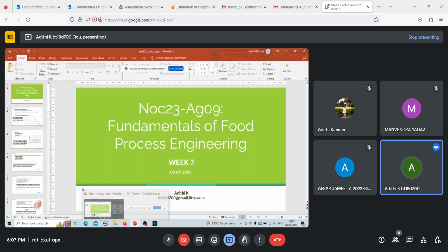So during the freezing process, the food is cooled to below its initial freezing point. That is what was A to S in the graph, if you remember. The freezing curve, A to S, is what happens when, during the freezing, the food is cooled to below its initial freezing point. Then the water remains liquid although the temperature is below the freezing point, and this phenomenon is known as supercooling, which may be 10 degrees below the freezing point as well. And this S point, or the supercooling point, is where the nucleation of the ice crystals begins.